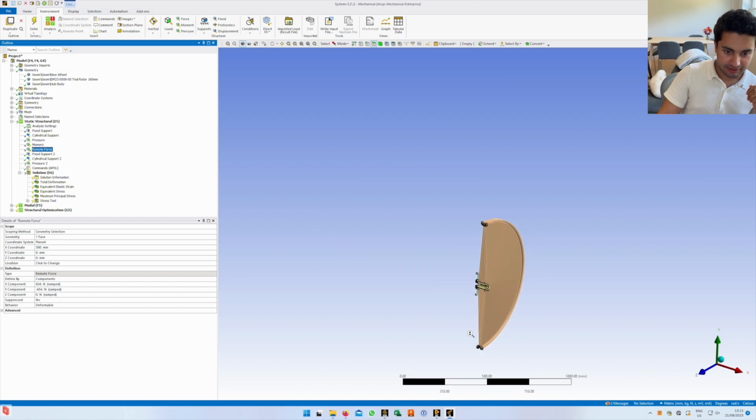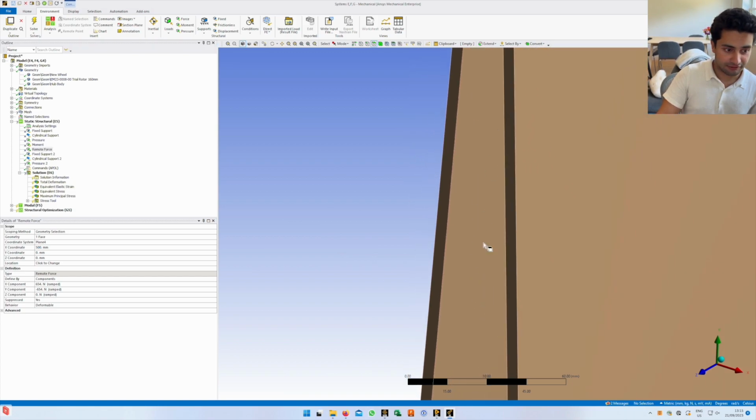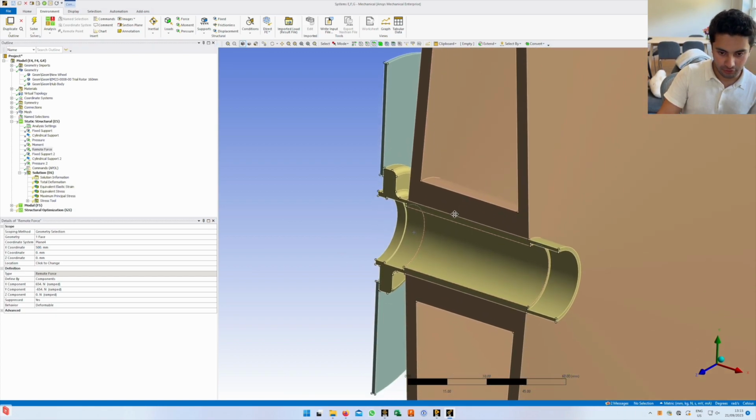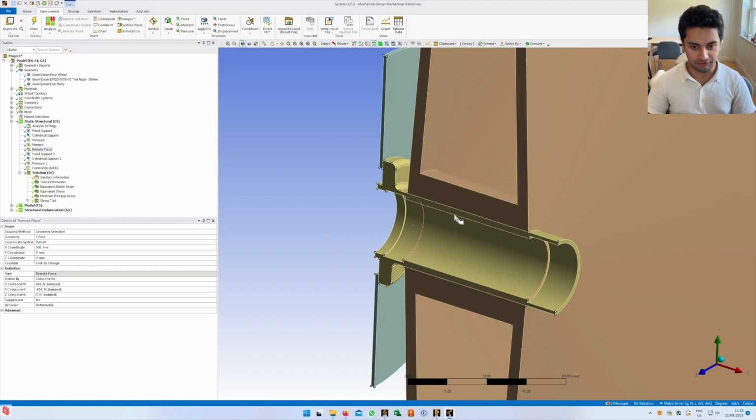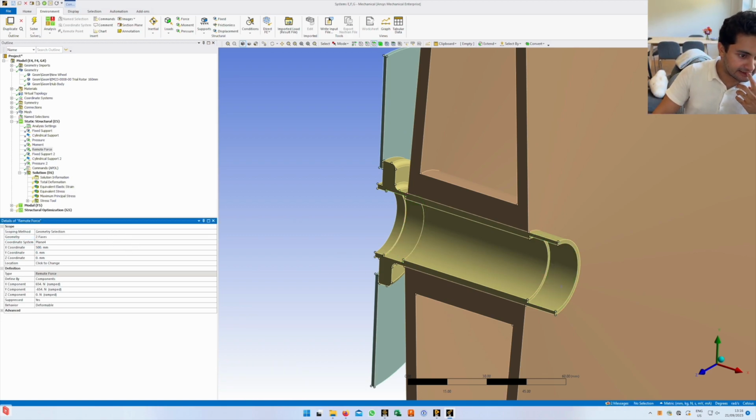So this is a force applied from a distance. It should preview, but it isn't. And this is the gravitational force and the lateral force. Those are both considered remote forces because they are essentially transferred from the axle, which lies on the bearings, which contact the bearing surfaces. So the faces I'll select here are the bearing faces, and again, pick a coordinate system if you want.